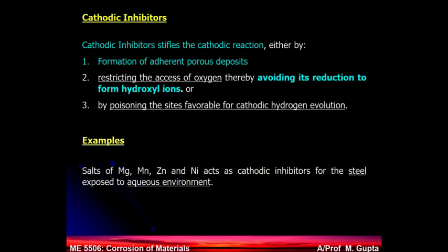Now let's go to the cathodic inhibitors. Same, they make some kind of a layer on the cathode, and once they make a layer on the cathode, depending on whether your system is acidic or alkaline, it will be very hard for the ions to reach it, even if this masking is not very good, even if there are some holes, but most of the area is still covered.